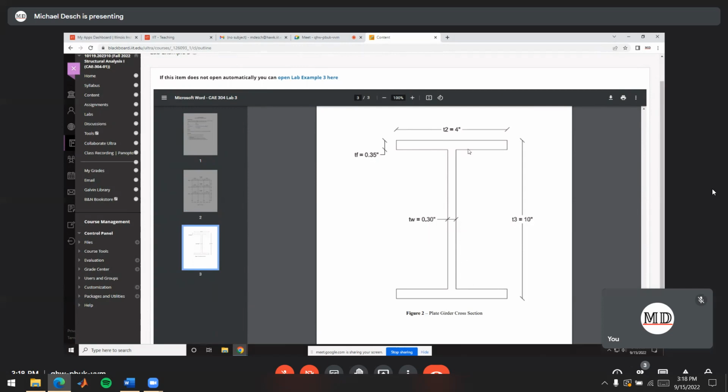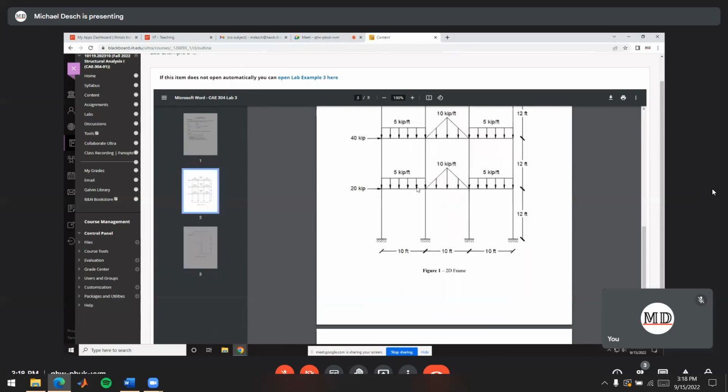So that's an option if we really need a deep beam here, or sometimes if you have like a transfer girder where you need to move a column over to another space on a lower floor, you'll put a really thick beam underneath it so it can move all that shear and moment loads over. And oftentimes plate girders are useful for that application because we need to be able to size them appropriately for the tasks. So any questions on the frame here?